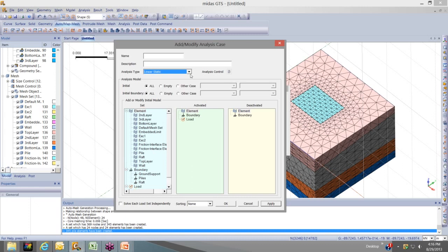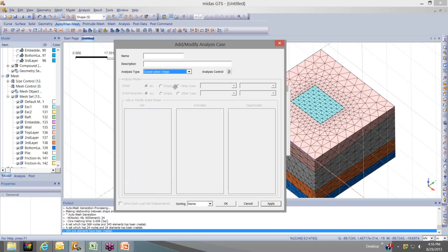And then later on, if you had a corresponding stage after that, you'd do deactivated segments as well. What construction stage analysis does for you is it takes different cases that are part of this timeline and puts them all into a single case to make it faster. So for smaller scale analyses, or analyses that would only require linear static analysis, this would be more ideal. But for longer sequences that require construction stage analysis, you can just define everything using the construction stage modeler, select construction stage, and you don't have to worry about these steps anymore because you took care of them in the previous step.